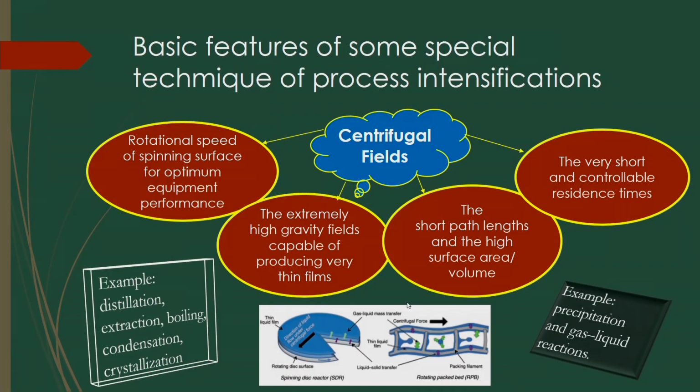Also, some catalyst particles will not reside in a column because they are much lighter than water. In that case, the inverse fluidized bed is also an important intensification of the process, where the catalyst particles can be controlled by controlling their movement in the downward direction against their buoyancy. So, that is why the inverse fluidized bed is coming.